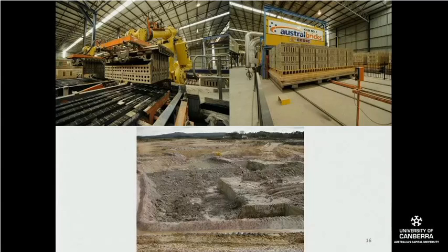The clay does not have a directional grain, but clay is famous for being able to hold on to water. So what happens is that you need to actually compress the clay to get rid of all the excess water in the clay before you form them into bricks and fire them.